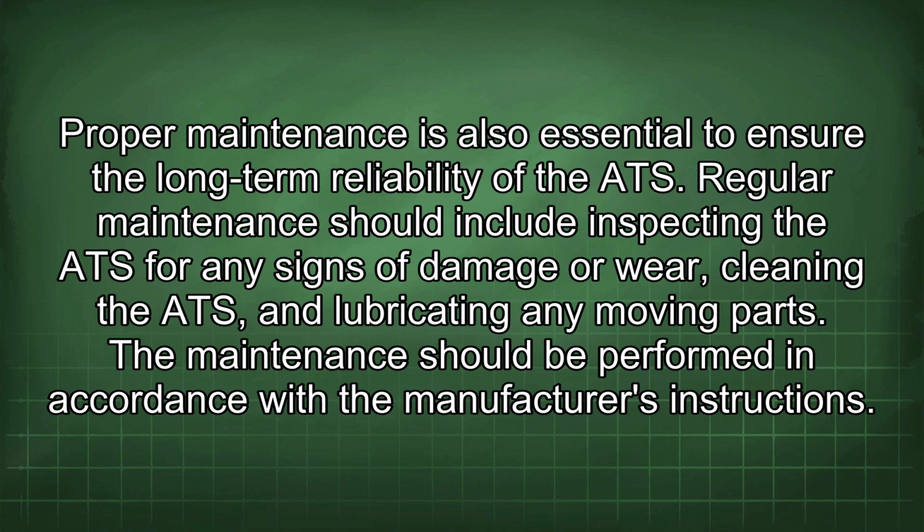Proper maintenance is also essential to ensure the long-term reliability of the ATS. Regular maintenance should include inspecting the ATS for any signs of damage or wear, cleaning the ATS, and lubricating any moving parts. The maintenance should be performed in accordance with the manufacturer's instructions.